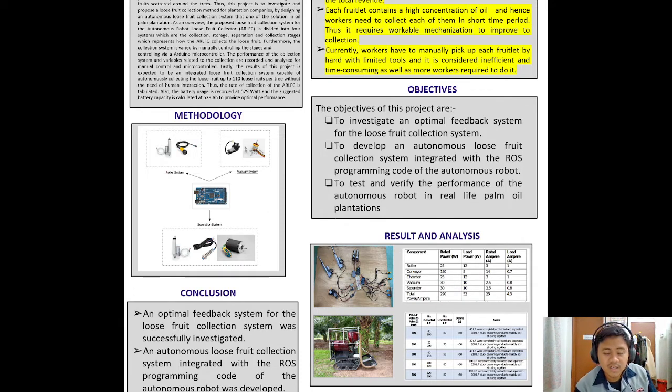The two IR sensors are used to detect the distance of the roller from the ground. For example, when the IR sensors detect that the roller is too close to the ground, they send a signal of 1, which is high, meaning that both the left and right sides of the roller are very close to the ground.